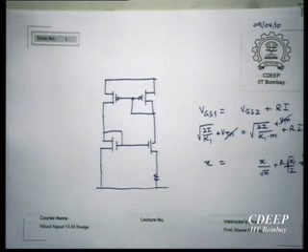Remember, what are we trying to do? We are trying to detect a current in the wire, the amount of current in the wire, and we are trying to bias this wire at some VDD by 2. That is what we said, right? We will hold this wire at some VDD by 2. That means simultaneously we are trying to read the current in the wire and we are driving it with a voltage. We are trying to keep it at a voltage, and at the same time, in keeping it at this voltage, how much current is flowing, that is what we need to measure. That is the circuit that we really want.